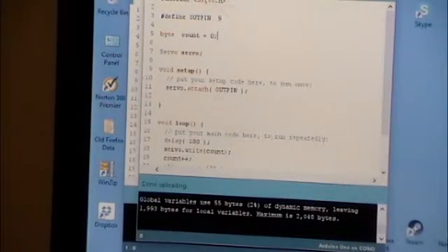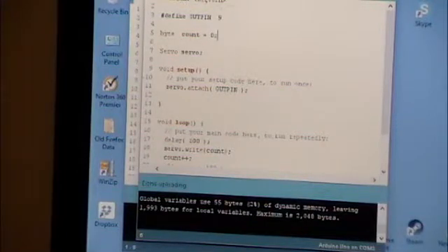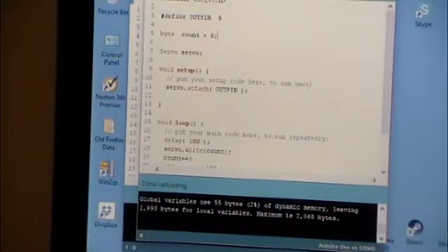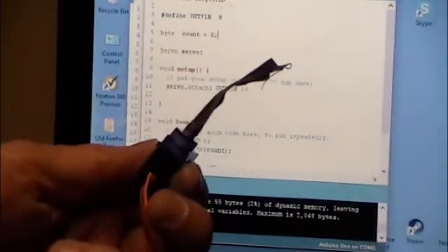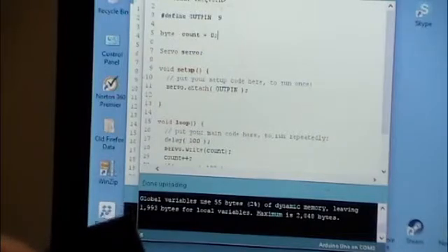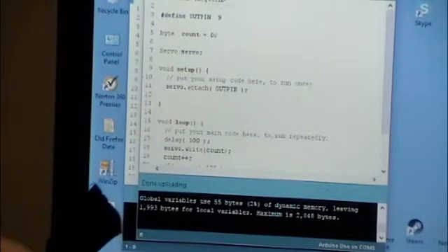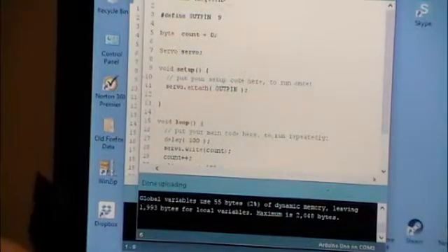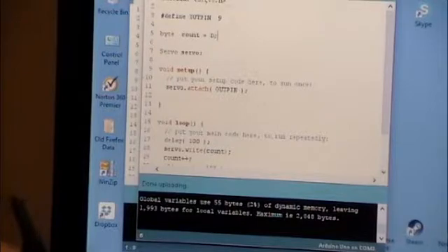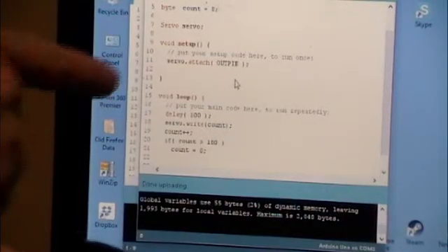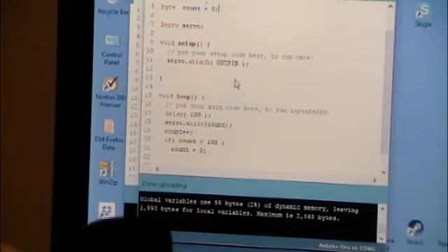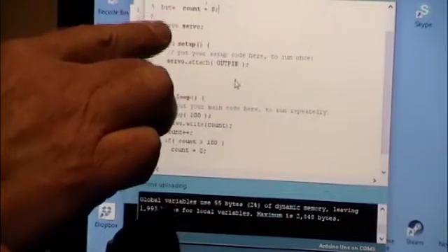So, servo on pin 9. So we've got the servo, and that should, like I said, I did not have a servo at home to play, so there we go. So we're counting, and we talked about it goes between plus 90 and minus 90. And so this is just using the servo library, and to use the servo library, this was really easy. It's 1, 2, 3, 4, 5 lines of code.